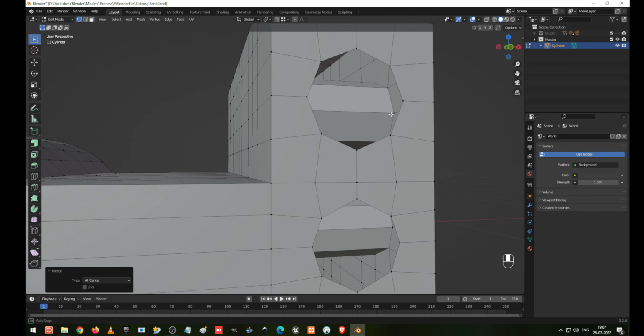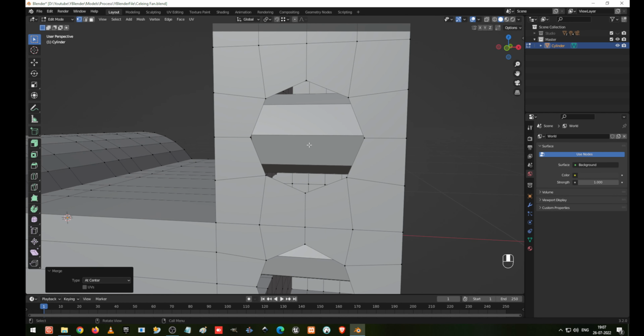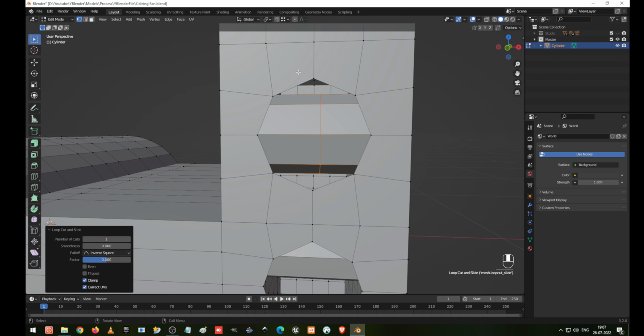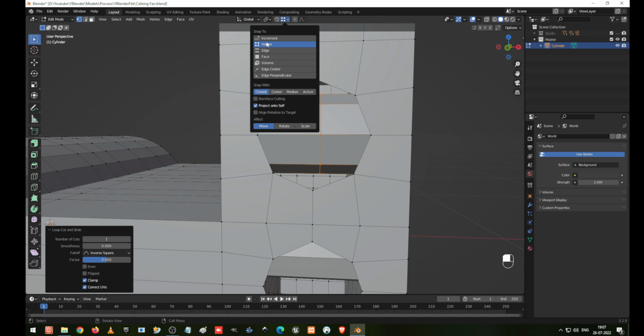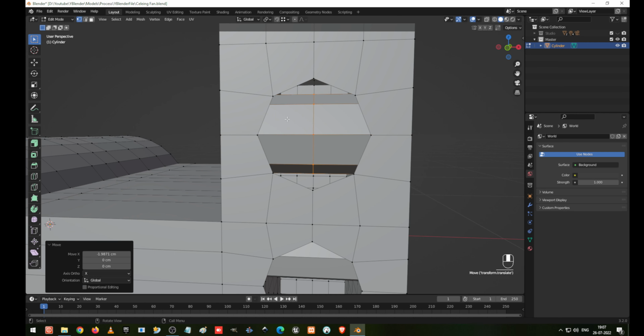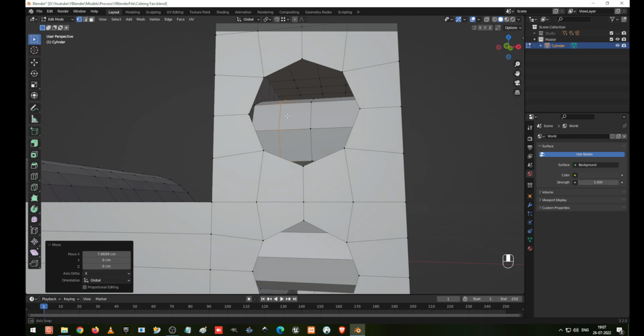Now we are going to join this hole to that hole. So how? Press R and create an edge loop in between. Now before that, do the settings. Vertices should be selected and closest move. Okay. G X axis, I use the Control key. You can see some circle is creating, so depending on that it will move. And I create one circle here, and G X and move. Oh, G X and move towards here. I hope it looks better.